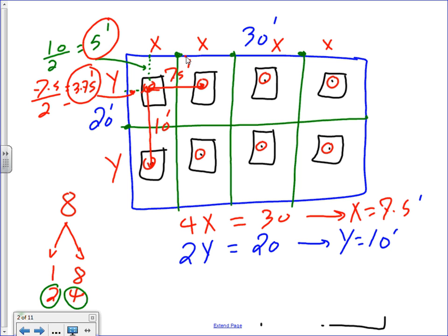Now here's Carrie. Carrie, why do you think I orient the fixture this way, not the other way around? The reason you orient them this way is because you orient them with the longer distance. Look at the longer distance. This is the longer distance here. You make the longer distance match the longer side of the fixture. Otherwise, you flip the fixture the other way. If it's a square, it doesn't matter. It can be either way. Can I have thumbs up, Chad? We fully understand how this works. Okay, so that's my calculation for my fixtures.